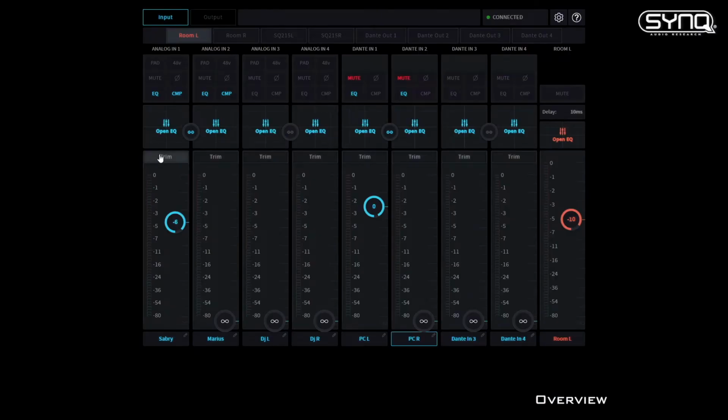In this case, you can achieve, let's say, a stereo mix, even if the channels are linked. As we discussed, you can set the trim by clicking the button and specifying the value. Of course, if I try to specify 30 dB, you see, the system is not going to allow me to do it. I can set like minus 10, and those parameters are linked. You can enable the EQ by clicking here. They are obviously linked. Same for compressor, polarity, mute button, they are linked, the pad.